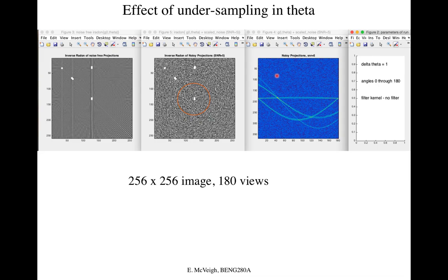We may also try a sliding window approach, where we find the variance within that sliding window. If the variance is higher, it means there's actually a signal in it, and otherwise it's noise and can be smoothed. Exactly right. If I slide my box along and keep getting the same statistics over and over, just do the average.